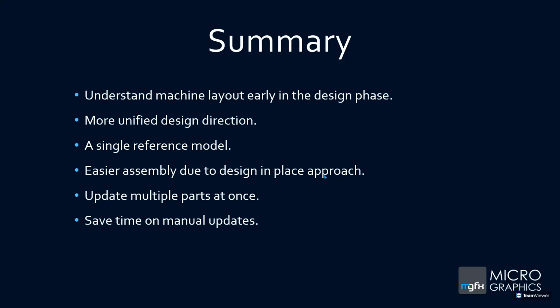As you saw with this design, I changed the width of the machine, and the base frame updated. I didn't even have to worry about that. It just updated while I was busy with everything else. And so basically it's saving you time on those manual updates. You don't have to go and double check everything. Okay, has everything updated? Do I need to go and update anything? Before release, you would still have to make sure, but you don't have to go and physically do every single little update manually.